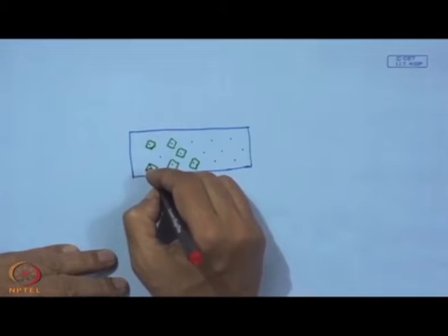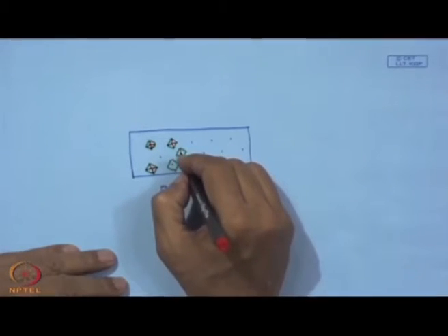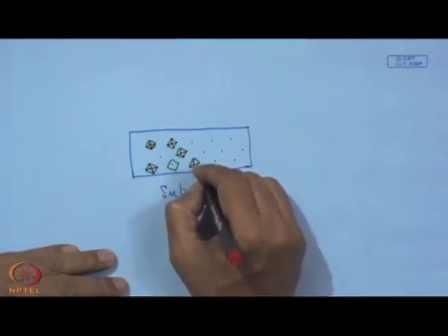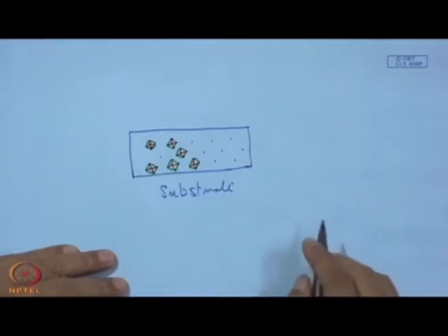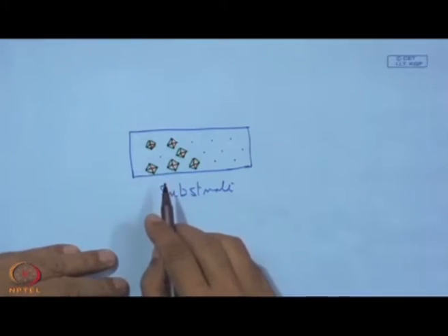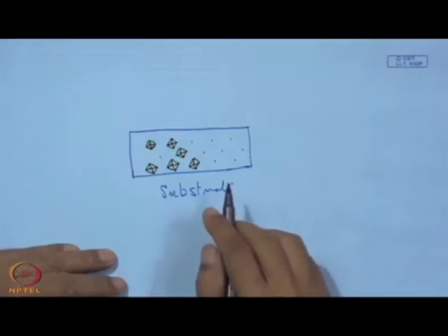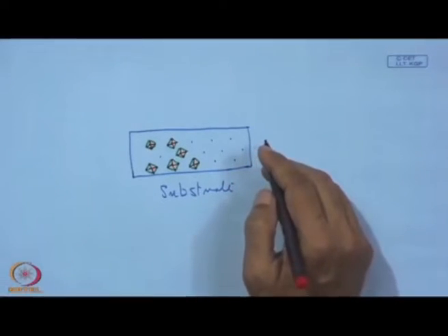So, this is going to be one diamond site, and these are not diamond coatings, but crystals individually grown just like this crystal, and this will become self bonded. We do not need any bonding material, neither braze alloy nor galvanic nickel. It is just on this substrate surface. Now, the chemistry of this substrate surface is very important, because it should be bonded automatically by natural bonding.